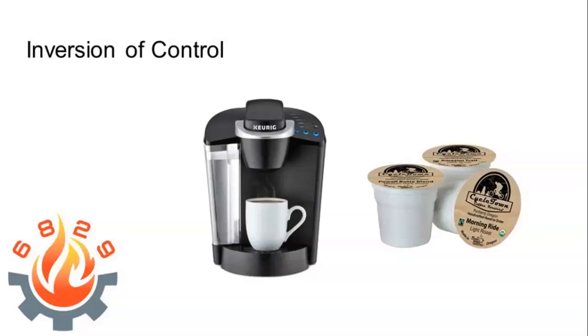So the question from Samantha: what's the difference between RobotContainer and Robot.java? Big picture, RobotContainer is what you're concerned about. It's like, I want to wire this to this, I want to put these two things together, I want this command and this subsystem, right? Robot.java is the connection from your robot code to the FMS. That's all pre-wired and you don't need to mess with it unless you want to do some advanced stuff.